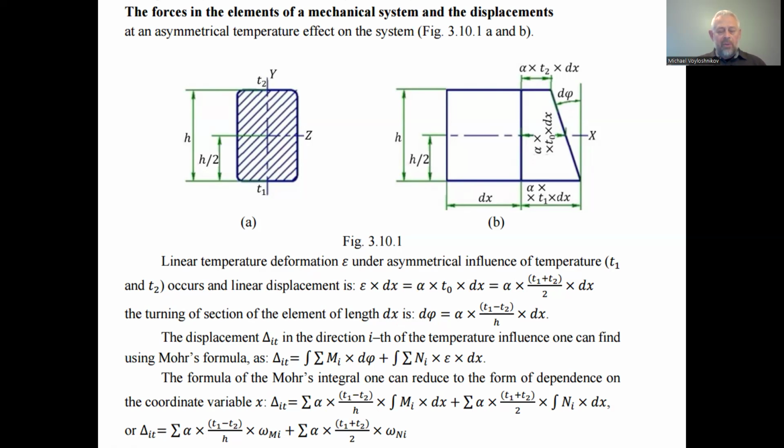displacements in all directions instead of the cut links when doing the main system out of the assigned statically indeterminate system. And besides, we have to find the independent summands, that is the free terms of the canonical equations of the force method, as well as the factors of the magnitudes of the forces subject to find.